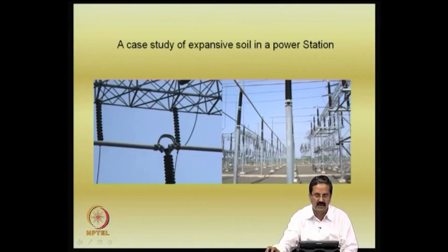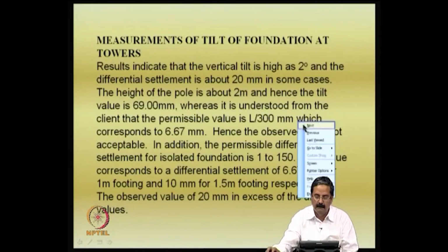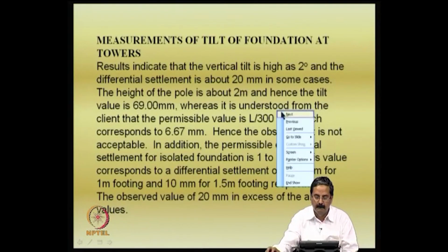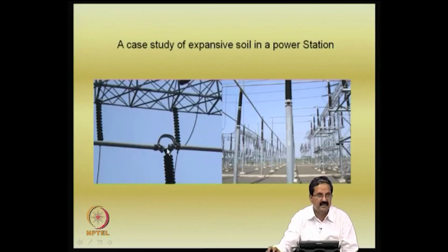what happened, the whole area got swollen. The expansive soil that is there in this area, you can see that this is also black color, this removed soil, it is expansive in nature, and you can see that it has resulted in deformations like this, right.